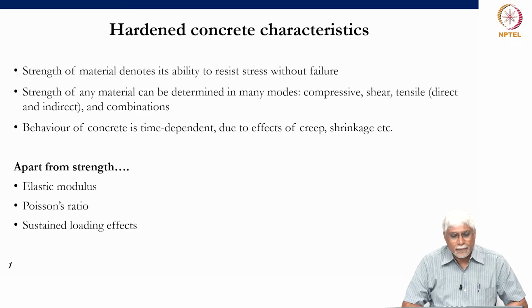However, strength can be determined in many modes: compression, shear, tension, and so on. Also, we should note that the behavior of concrete, as many other materials, is time dependent. In concrete, two time dependent strains or modes of deformation are shrinkage and creep. We'll talk about this in detail a little bit later.